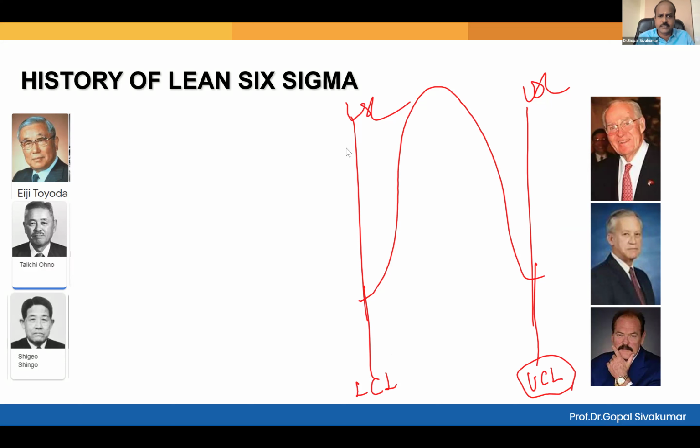By birth, all of you are getting this height. Am I right? They are not decided by you, but they are natural limits. Very good. Upper control limit and lower control limit. And this length between upper control limit and lower control limit is known as process spread, which is 6 sigma. And what is this length? The tolerance given by the customer, which is USL minus LSL. Yes or no? This process just made it. Am I right? This is just a capable process.